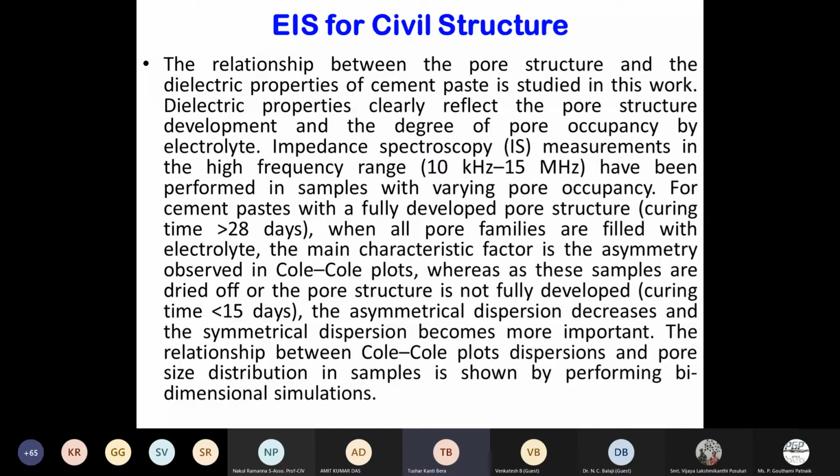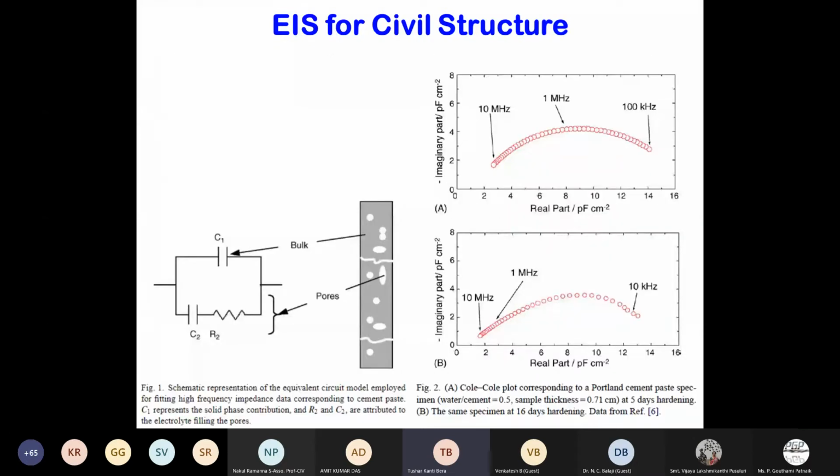And also if we have a higher frequency, there will be the possibility of getting more information because we will be scanning a material with a wide range of frequency. So definitely we will be getting some more information. And they also studied the Cole plot, and they found some results, and they detected some electrical behavior, that is capacitive circuit, and the capacitive circuit similar to the cell or tissue structure whatever is studied in biomedical. And also they found that the impedance, the real part and imaginary parts which are varying over the frequency, it is also performed in the place of the concrete structure also.